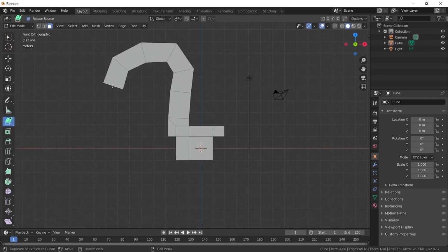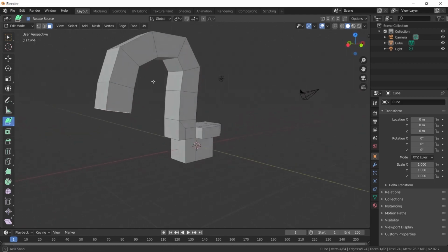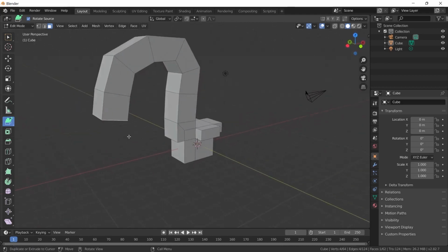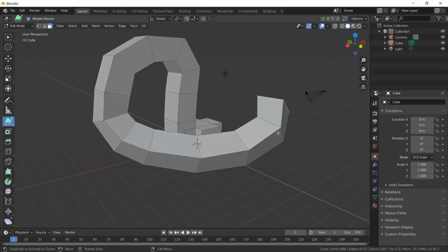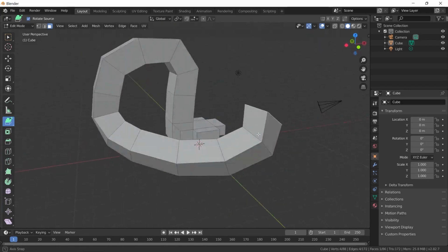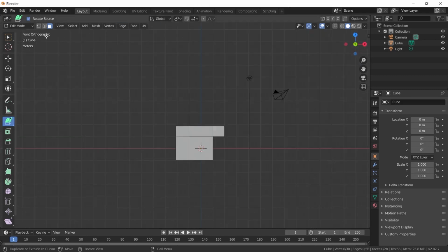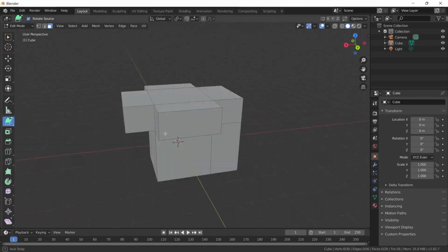It doesn't make much sense to do this in perspective. So we need to do it in full lateral planes or in views like bottom, so that we can get an accurate result. In this way, it will automatically extrude where we click. If we try to do it in perspective, it will be a bad situation. See, we may not get the result we want because it will not operate according to this perspective. This is why orthographic views are important rather than perspective.